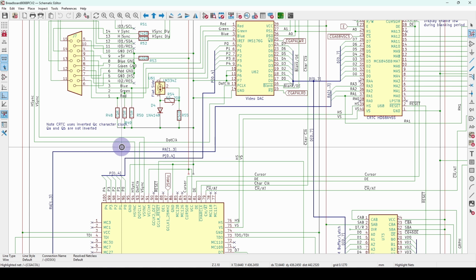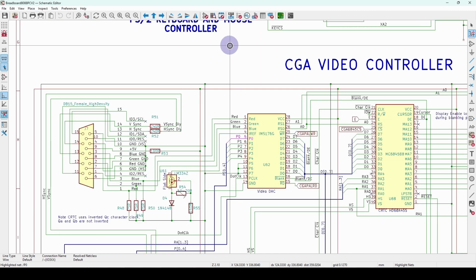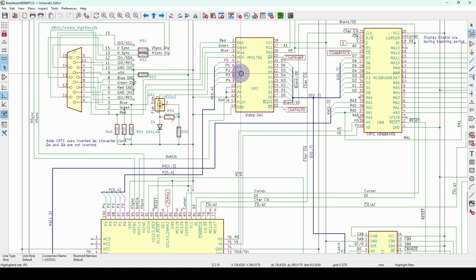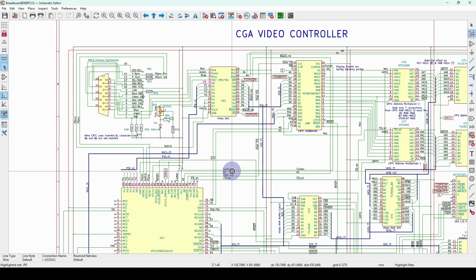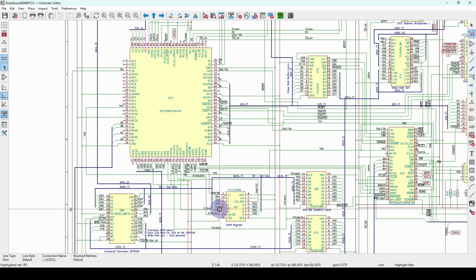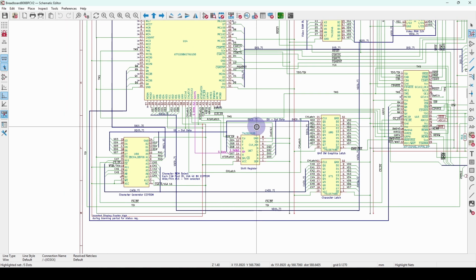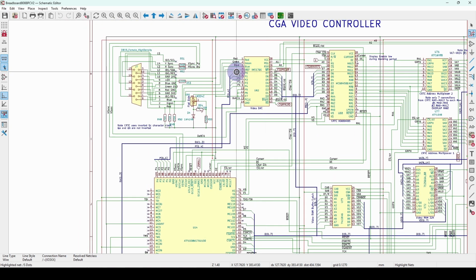And then we're going to need to connect the color outputs here. So the P0 to P4 color outputs are going to feed into our video DAC here. Now, up till now, we've just been feeding the inputs here either from the address lines to get our different color bars coming out, or in the previous video we just toggled the P0 value by the output of the character generator. So down here where our S dots came out, we just hooked that into P0.